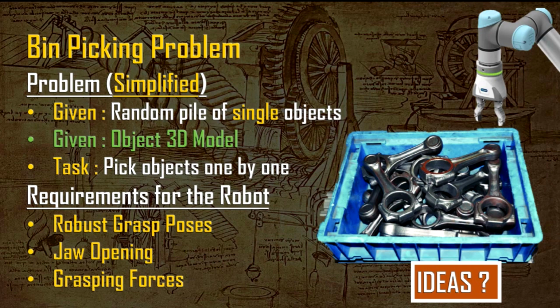Yes, that's a very good point, and your question is exactly valid: how you can capture the position at the moment the objects are being picked again and again. As already discussed, one of the best solutions from the industry front is a 3D depth camera. You will use machine learning and computer vision algorithms to identify the object position with respect to the 3D world, not just the 2D world, and it can also give you the orientation.